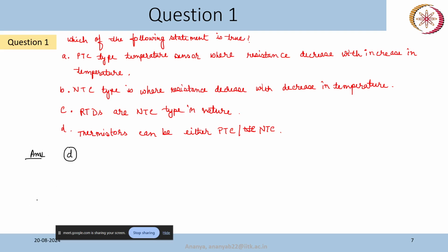In PTC type sensors, as the temperature increases, the resistance of the sensing element also increases. In case of NTC, negative temperature coefficient, as the temperature increases, resistance decreases.